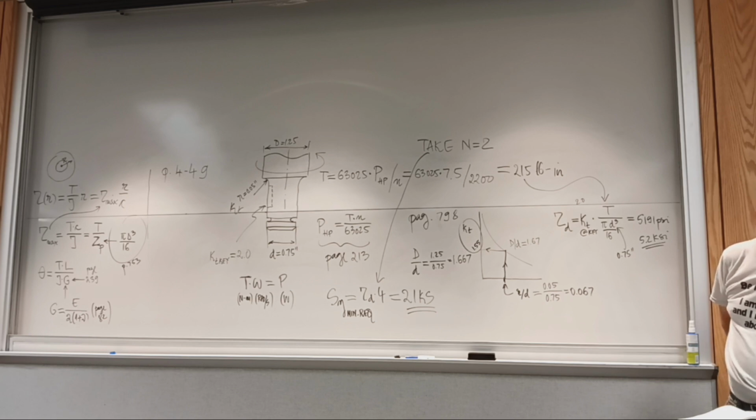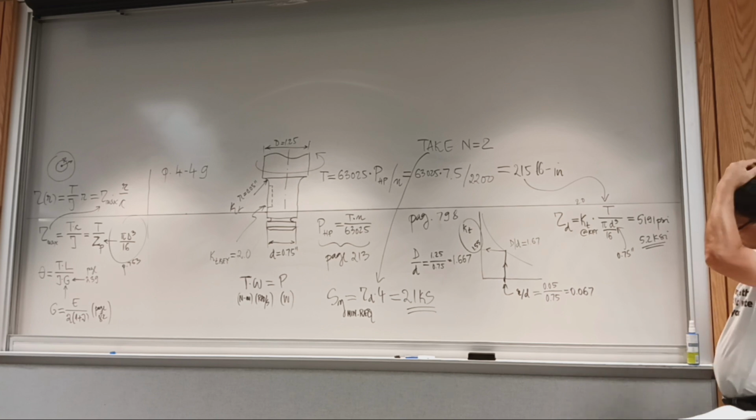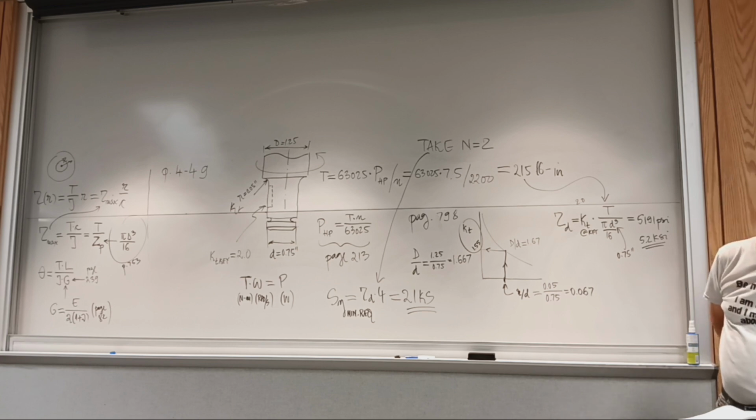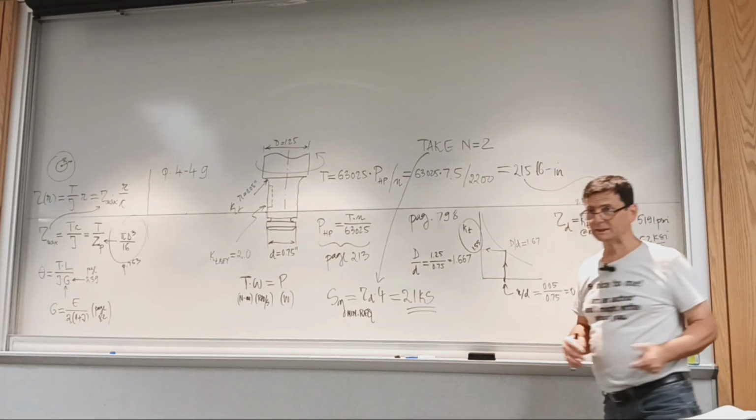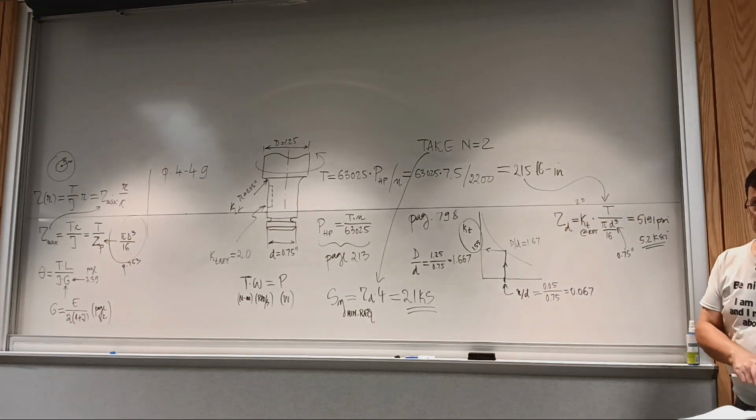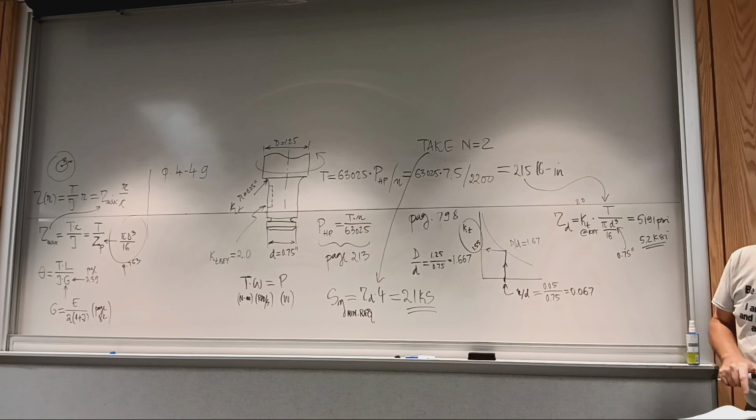And we can go with one that is 1040 cold drawn, for example, easily. It's 97 ksi. So from here on, you start thinking about other implications like availability and machinability. So if it's cold drawn, it's easy to machine.